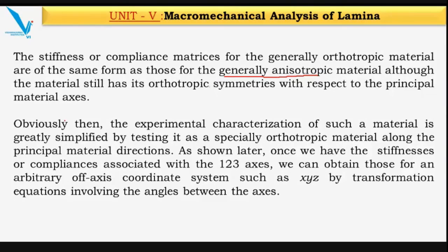Okay. So obviously the experimental characterization of such a material is greatly simplified by testing specially orthotropic material. Then I will show you that by testing the specially orthotropic material, analysis can be done for such material also by taking the off-axis coordinate system into picture, means by transformation of the coordinates.